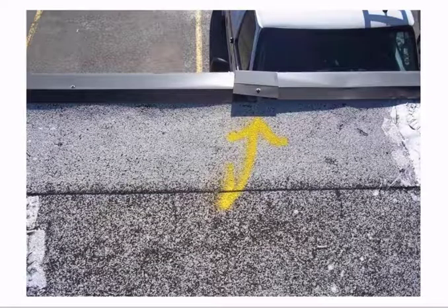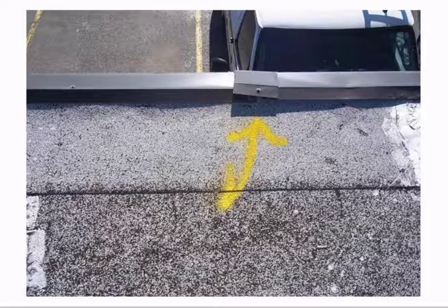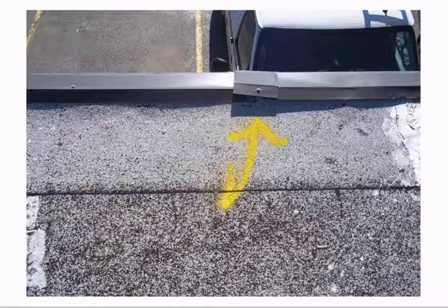Well, here, Nick, we have an edge metal system that looks like it ran short. So they just put a little piece over the top. That could be what we call an exterior splice plate. It could be just an added piece because they were 3 or 4 inches short. I'll give them the benefit that the exterior splice plate, and those are good in the short term.